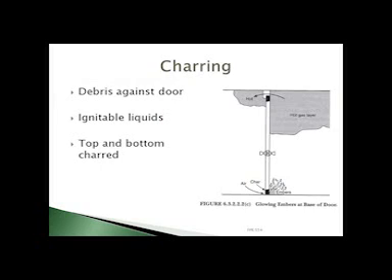And then if debris is placed next to the door is another thing to look at. This is mainly to see the difference between a fully involved room and a room with something burning next to the door. They'll have similar results, but a major difference. So as that debris gets next to the door, like the first room, the hot gas escapes through the top of the door, and it starts charring the upper portion of the door. The cool air is drawn underneath the door.